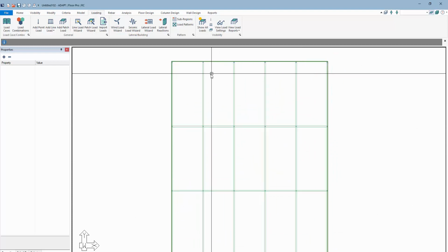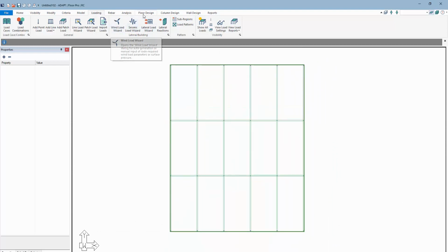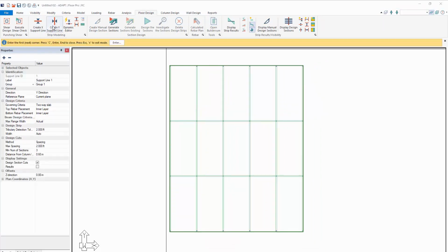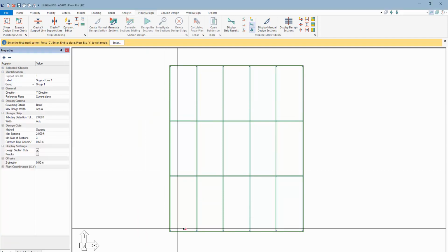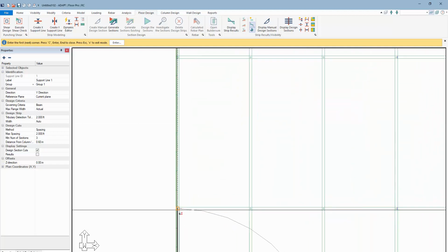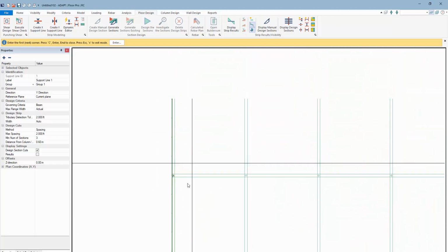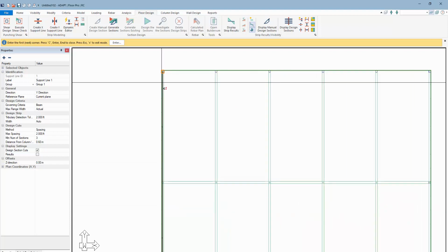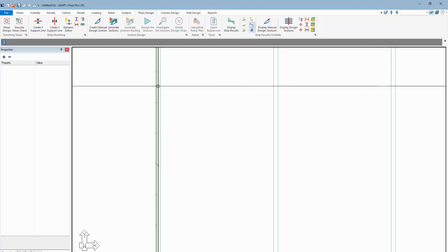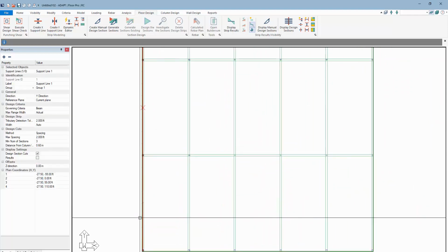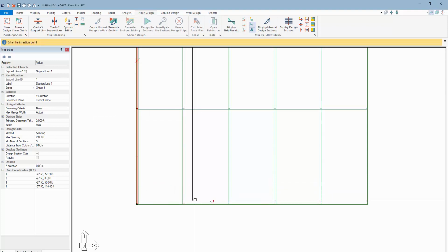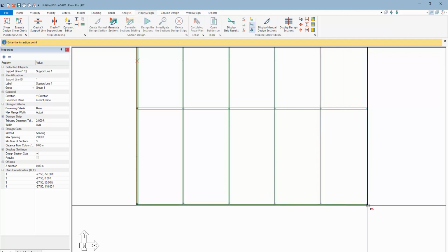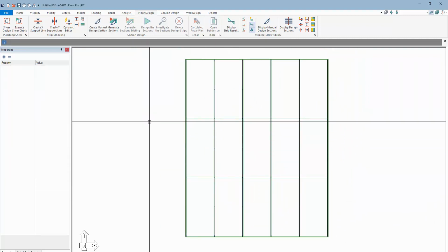And then finally, we're going to add some design strips. So I'm going to go to floor design. I'll select the Y direction, and one other thing that's coming in the 2020 version is this property grid. I could go to criteria and just change this immediately here to beam, and that allows me then to make the modification without going into the properties dialog window that's used in the current version of the software. So this is also something that will make life easier for users, being able to quickly make modifications to components in that environment versus property windows for selected components.